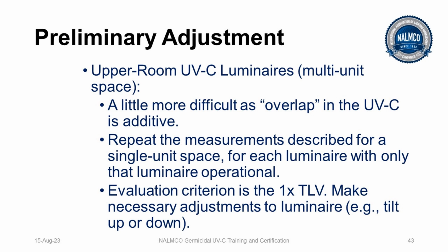And I'll use the criterion of 1 times the TLV, or in the case of 254, it would be 0.1 microwatts per square centimeter for 8 hours. I'll also tilt the meter up and down a little bit to see if something funky is happening in terms of reflection.